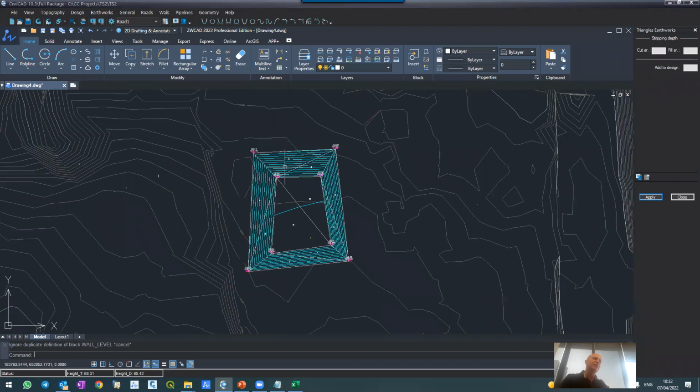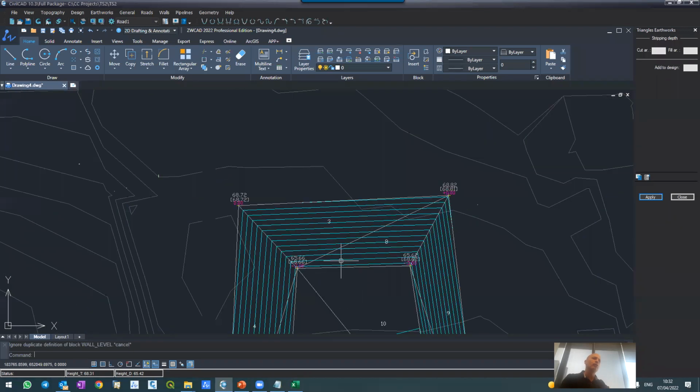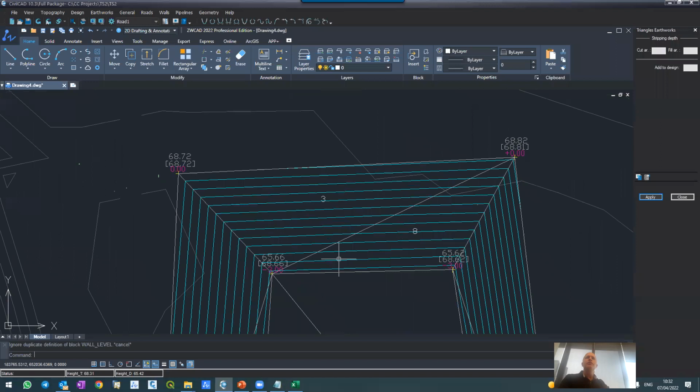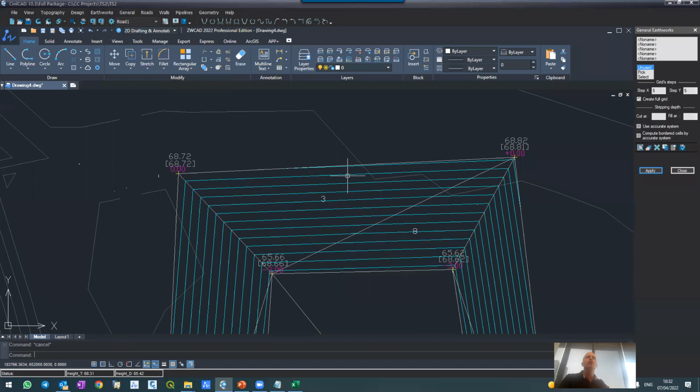I'm just giving you some hints, and I want to continue and show more features. I cannot say what is better. I know that earthworks general is the most accurate because we create a very small grid that reflects every change in the two surfaces. But obviously, if you create a grid of 10 by 10, it will not be accurate, and the same problem applies to the triangles. So what is better? It's a good question. Everything starts with earthworks general. It's the most accurate one.